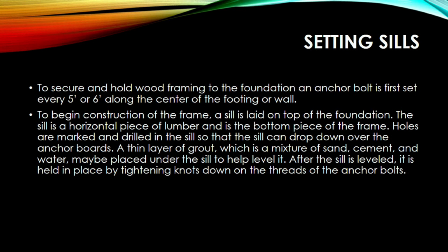Setting sills. To secure and hold wood framing to the foundation, an anchor bolt is first set every 5 feet or 6 feet along the center of the footing or wall. To begin construction of the frame, a sill is laid on top of the foundation. The sill is a horizontal piece of lumber and is the bottom piece of the frame. Holes are marked and drilled into the sill so that the sill can drop down over the anchor bolts.